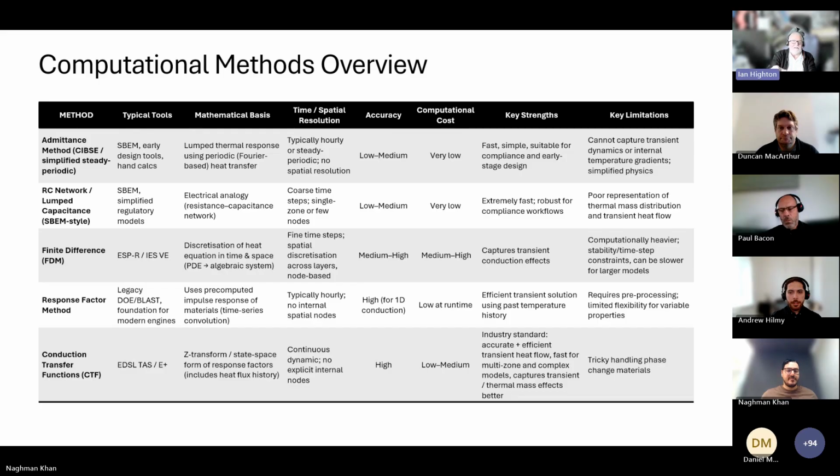And if you get it even slightly wrong, you can just end up ping-ponging backwards and forwards between the two. I've got to stop telling people technical things, but the airflow network says, no, the air's got to do this, and the thermal goes, okay, you do that, and then I'm going to change the temperatures. And once the temperature changes, then the airflow changes, and you can end up in a very unstable situation. So making sure that converges and converges in a reasonable space of time is tough. That's way too much detail for everyone, apart from maybe three of us.